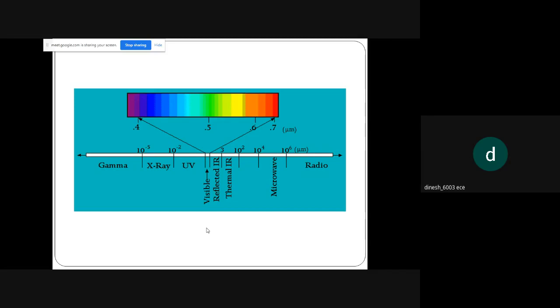And the spectral range 0.52 to 0.59 is used for vegetation vigor, rock or soil discrimination, turbidity, and bathymetry in shallow waters. In 0.62 to 0.68, strong chlorophyll absorption leads to discrimination of plant species. Whereas above 0.77, the delineation of water features, landforms, and geomorphic studies can be done.